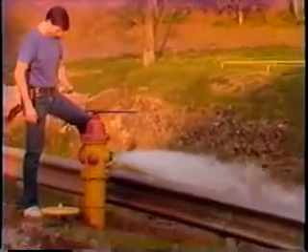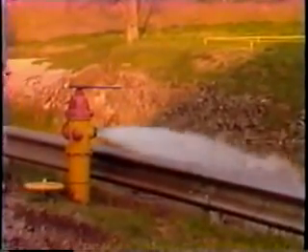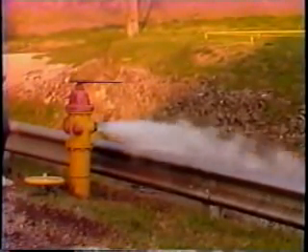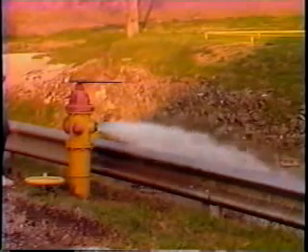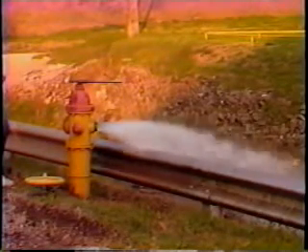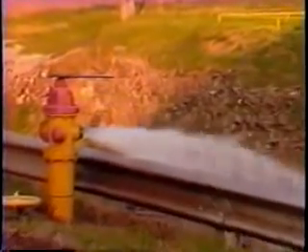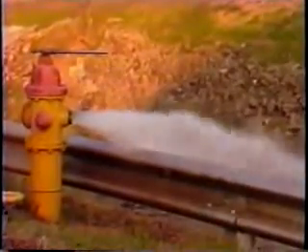During a hydrant flow test, you should expect to get several hundred to over 1,000 gallons per minute out of a flowed hydrant. If you're only getting 100 or 200 gallons per minute out, as you see here, it's usually an indication that something is wrong during the test.